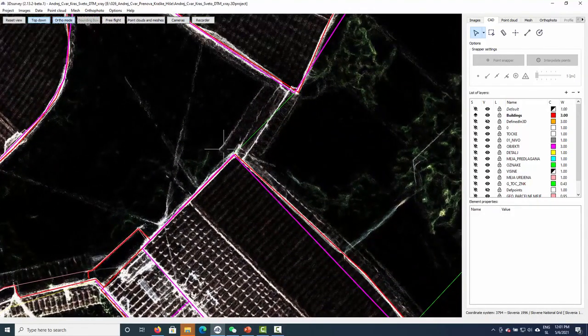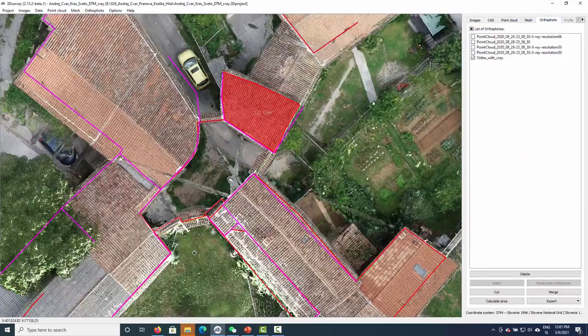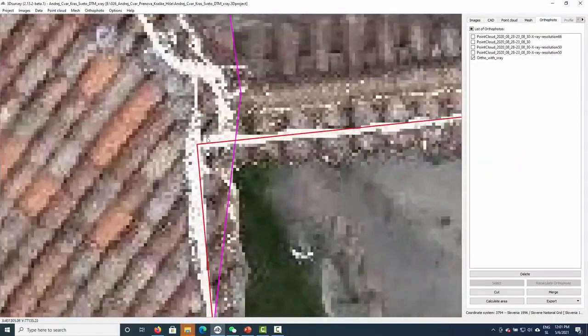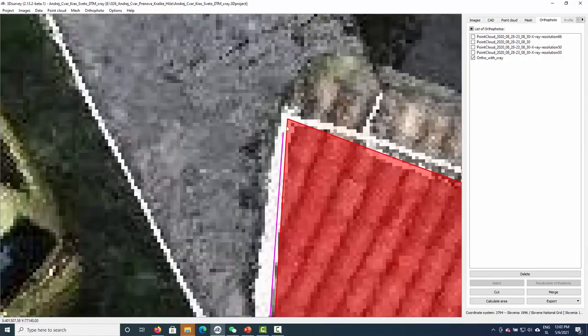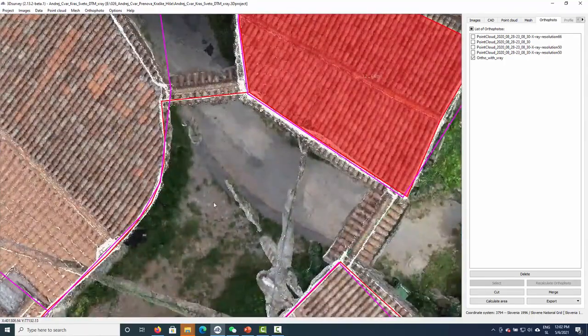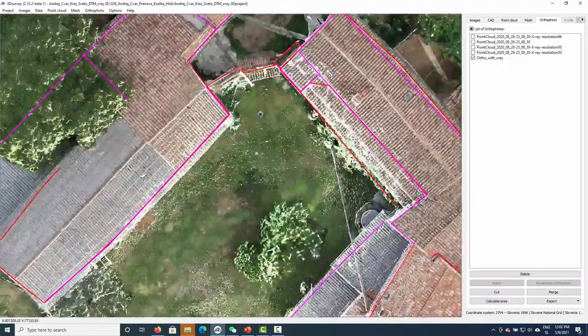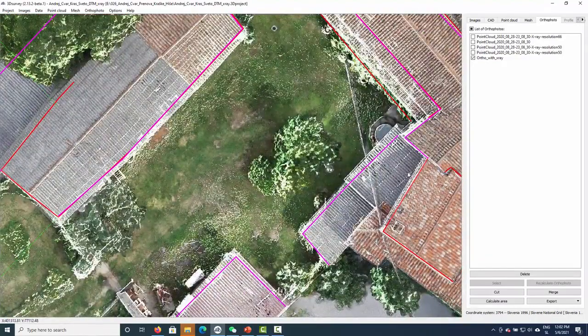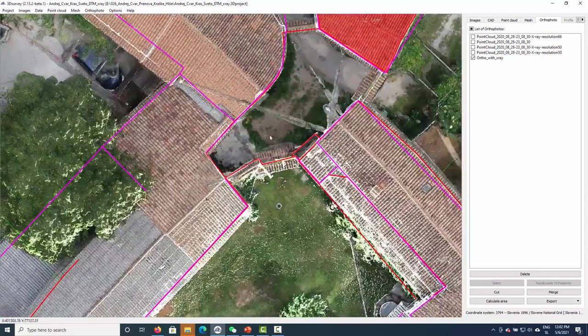What we can do now is we can check what kind of differences we have. If I zoom in here, so here was a point measured, so this corner here, we see that here we maybe have about 2 centimeters of difference. Okay, so here was the point measured by a land surveyor and here's ours, so they are pretty similar. I would say that ours is the more accurate one, but of course here the land surveyor struggled because probably he had his station in here, so from here he was able to take most of these corners. Then he probably moved in here in order to take the corners that are visible inside of this courtyard here.